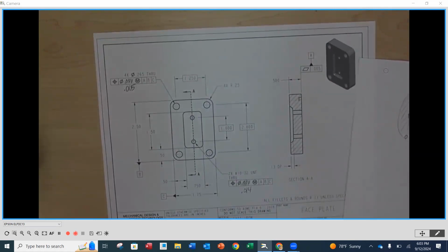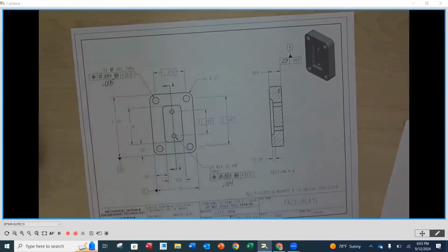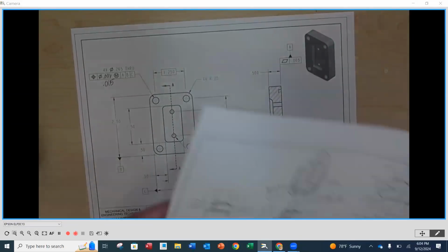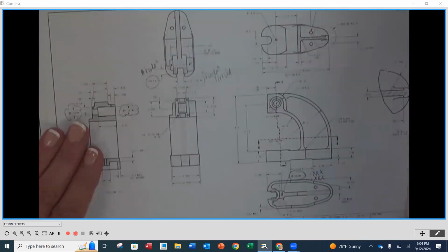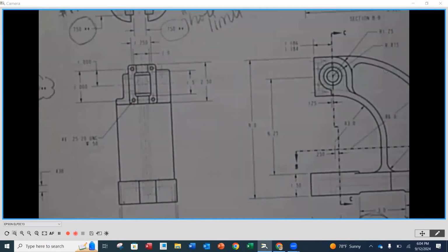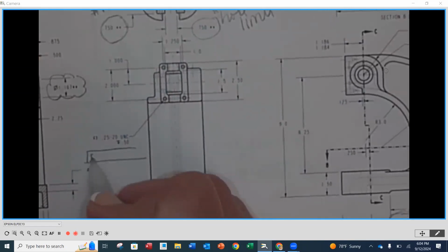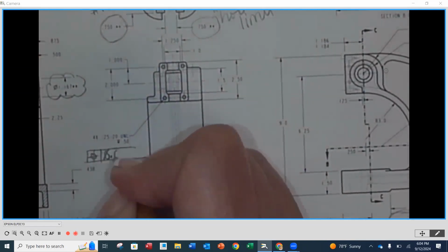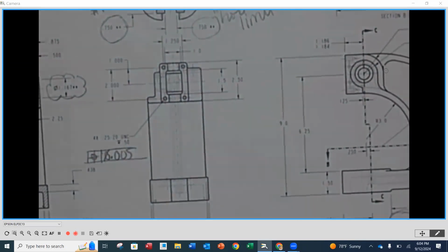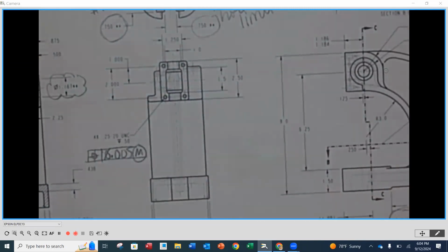fixed fastener situation. Now, I've got this whole location here, and these are going to thread into these holes right here, right? That's what's nice about this, it becomes really easy. So now we're going to take that very same value, the very same feature control frame. This is going to be a position tolerance, and we're going to use the diameter of 5 thousandths. It's going to go right in there for our value. We're going to use the maximum material condition, okay?